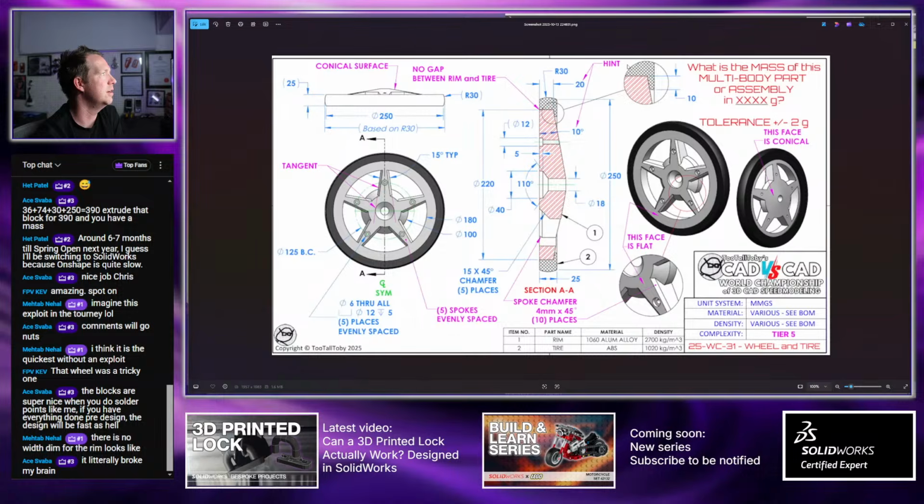The hint here is telling you actually how to sketch this. You've also got the 220, which is that section, and then you've got the 250 for the outer bit plus the arc. You're assuming that the two outer points of the arc are both horizontal, not one higher than the other. So once you put the radius dimension in and you've got those outer points, that can work quite smoothly. So yeah, it was lots of fun watching the replay of this one. Arte and Sebastian both neck and neck.